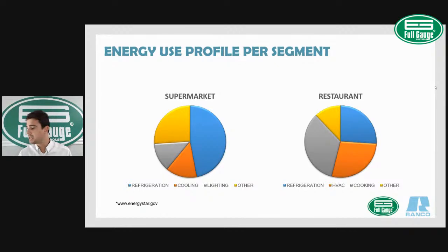In addition to that, once the electric heaters are on, they draw a lot of electricity. Also, some of the heat that is created at the coil gets transferred to the refrigerated space, and eventually you're going to have to remove that heat from the refrigerated space. So there is another energy expense right there. To sum that up, that's the importance of having a precise and efficient defrost cycle to optimize your energy consumption and increase the life cycle of your equipment.